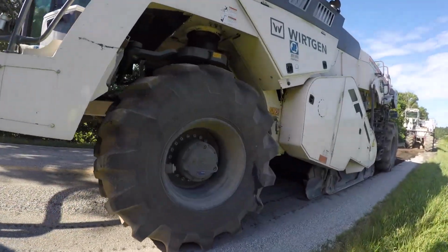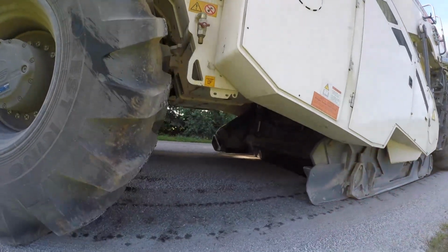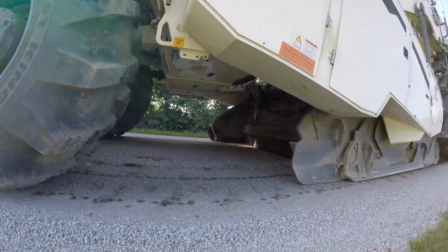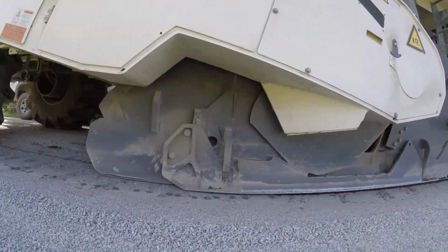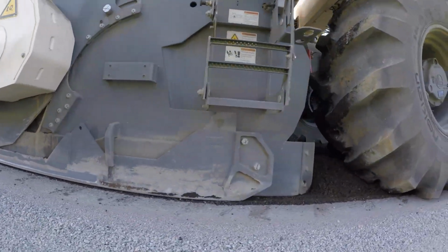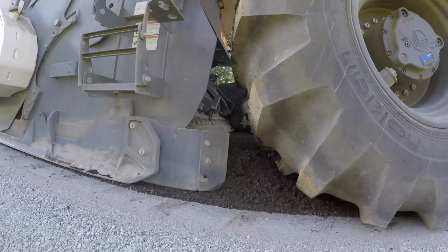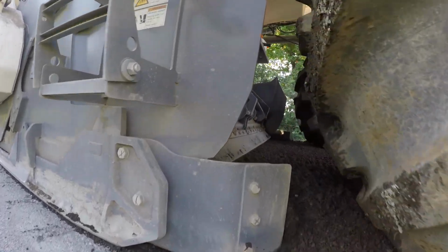You're able to take a secondary road or highway application or primaries, but secondaries are notorious for turtlebacked options, and it needs to be wide, and you have an 18-foot section, a 20-foot section, and you need consistency throughout that road. You need a 2% or maintain a 3% cross slope. You need to put a super in. Well, this is where you do that.